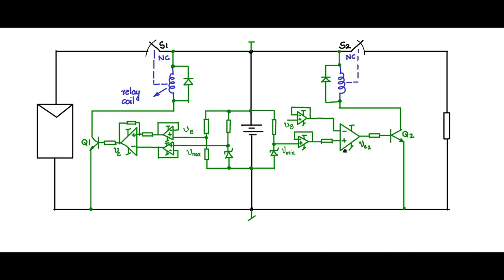Here also we would like you to use hysteresis. So you can connect a resistance between this and the output and have a hysteresis, because as soon as this is opened, there will be a shoot up of this voltage and again chattering will result. Therefore, it is good to connect a resistance across this and put a hysteresis so that the trip will occur even if the voltage shoots up. Then the trip will come back depending upon the lower trip point and the upper trip point determined by this hysteresis.